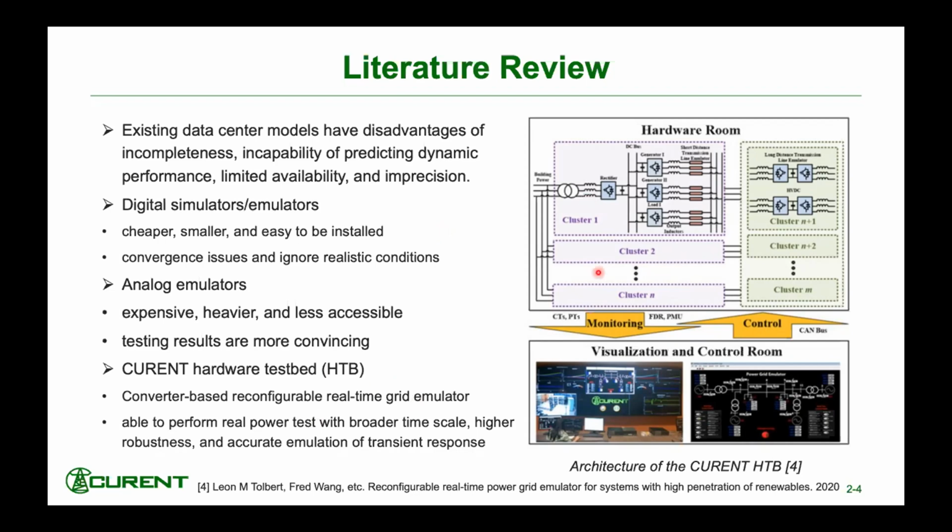The HCP platform, as you can see here, is based on multiple converters, and by programming the interconnected three-phase voltage source inverters, we can emulate different power elements, such as the generator, battery energy storage system, and various power loads.